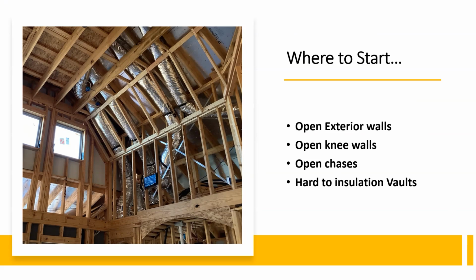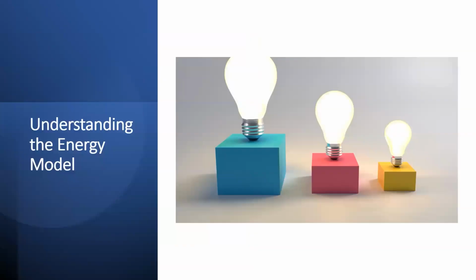You have to walk outside and look behind every single one of those walls to make sure it's done correctly. But open exterior walls, open knee walls, open chases, hard to insulate vaults. This is just a nightmare, in my opinion. This is a Halloween-worthy picture when you walk into an inspection.